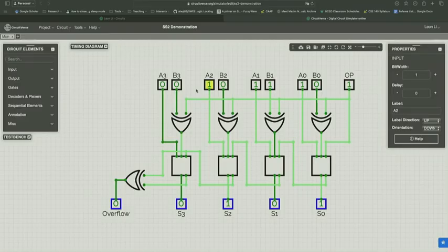That is the overflow detection for two's complement. So for now, you can ignore it. That is something that you will implement in your workbook. But the reason why we have an XOR gate is roughly as follows. The most significant bit of two's complement determines the overflow condition. If you add together two positive numbers and get a negative number, so 0 plus 0 gives you a 1, that's an overflow condition. You can describe the overflow condition in terms of the 2 input bits and the single output bit. Those 3 bits going through some gate, some logic, will give you the overflow detection logic.